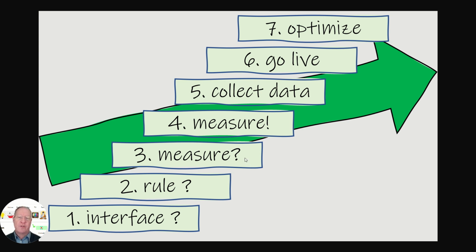The second item is to identify what you need to know and what you need to measure to support the rule. So usually there will be a few things which you want to measure. Motion detection can be a measurement, temperature can be a measurement, brightness, things like this. So once you have identified what you need to measure, you should actually introduce the measurement. So not the smart routine, you introduce the measurement and you test the measurement, whether the measurement results are consistent and logical and correct.